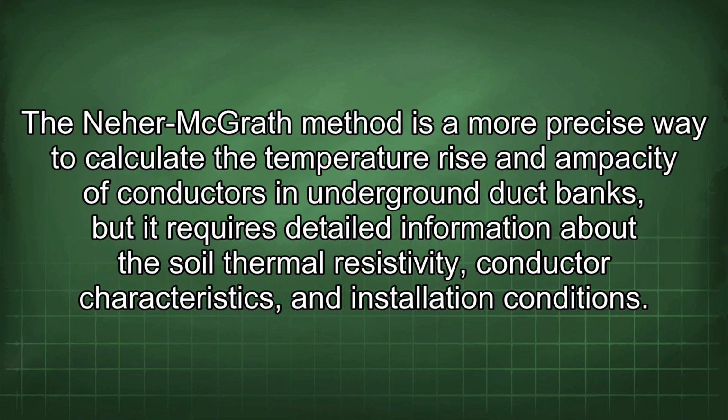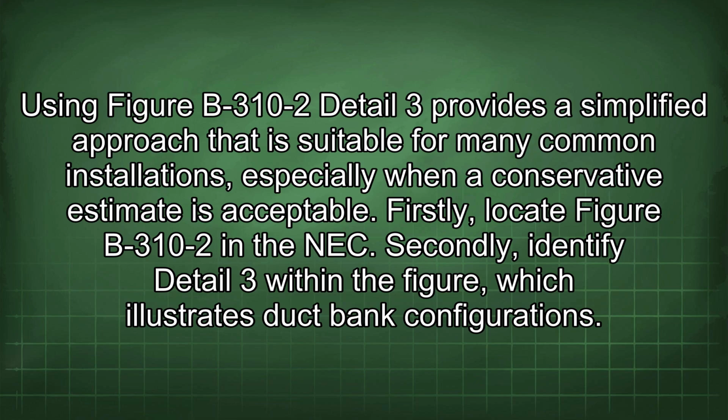The Neher-McGrath method is a more precise way to calculate the temperature rise and ampacity of conductors in underground duct banks, but it requires detailed information about the soil thermal resistivity, conductor characteristics, and installation conditions. Using Figure B-310-2 Detail 3 provides a simplified approach that is suitable for many common installations, especially when a conservative estimate is acceptable. Firstly, locate Figure